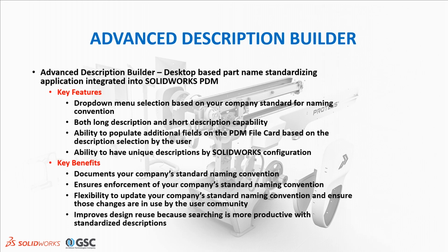Once you have your company standard established, you load that into an Excel spreadsheet in which Description Builder reads that standard in and provides a menu selection for the user in a drop-down capability. You also have the ability to have unique descriptions by SOLIDWORKS configuration.